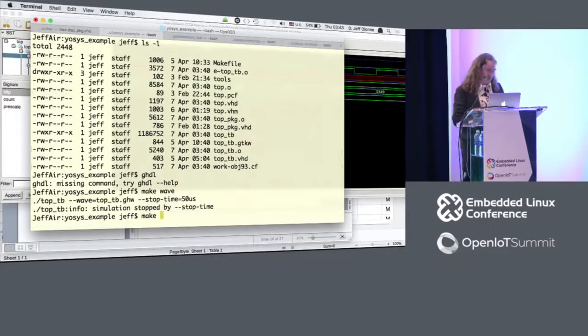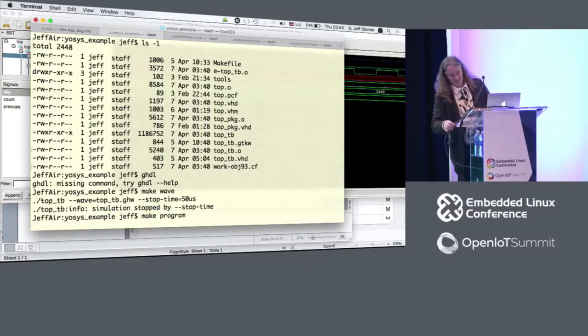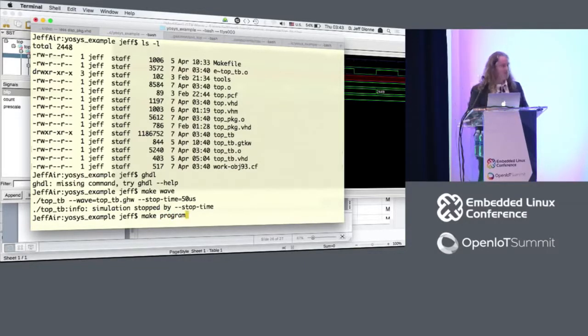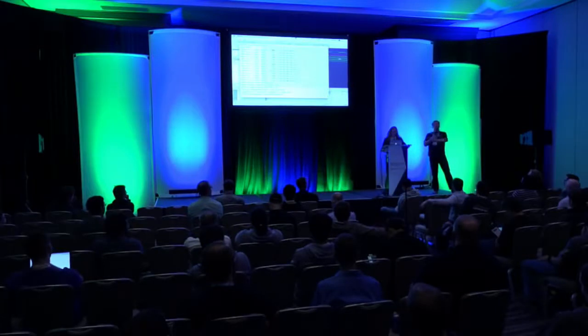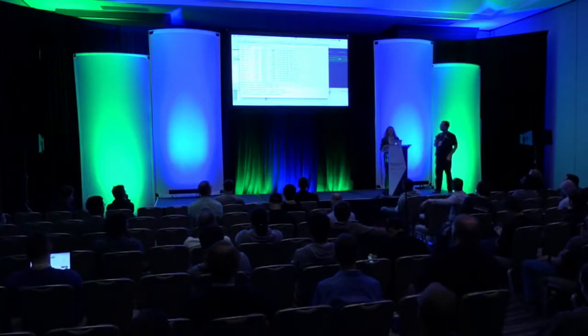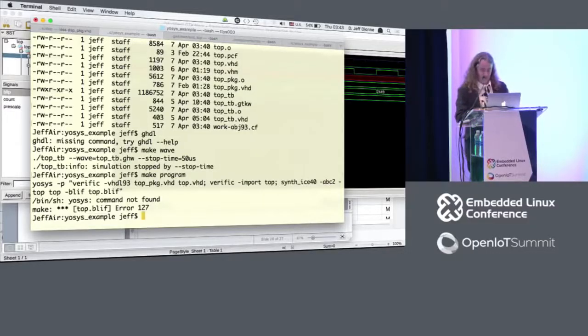Yeah. Right now, what we're using is the compiler for the big FPGAs from this company is a free download from their website, right, but it's closed source. The compiler for these small FPGAs from the other company, we can do an open source toolchain, although we got to mix and match bits from various things and need a little Python glue in the middle. But the complete open source toolchain targets FPGAs that are too small to run this chip. It's like there's work to do. So let's make a synthesis and program the actual, whoops.